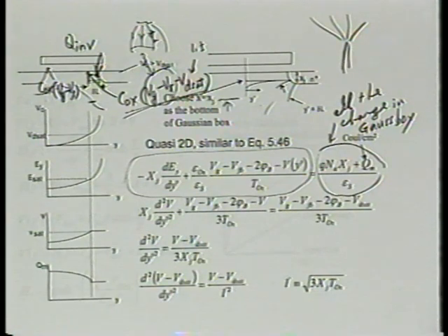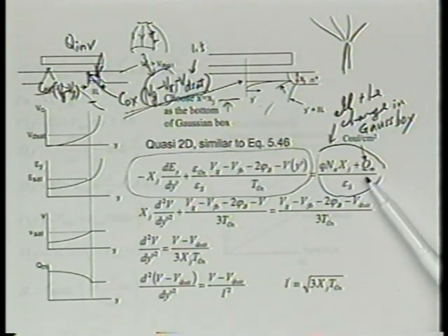Particularly, we have to remember the charge densities throughout this channel, including the pinch-off region, may not differ that much from source or drain. May not. Is it okay now? So hopefully that will really shatter this concept of the pinch-off region. What is pinch-off? Do we really not have any mobile carriers, or do we have lots of mobile carriers? Okay, so let's agree we have lots of mobile carriers. Then we cannot ignore that in the charge term within the Gaussian box. Is that right?